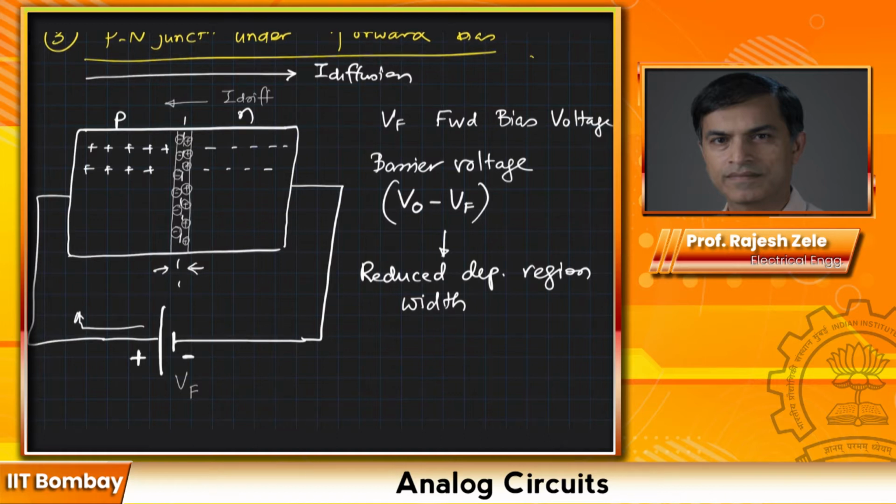All right. So this becomes very interesting now when you put all of it together. What's the interesting part? If you forward bias the diode, you will have current flowing from P to N, from positive terminal to the negative terminal. But if I reverse bias the diode, there will not be any current flowing. Okay. So the flow of current is unidirectional. It's only in one direction. It will not flow in both the directions. Okay.